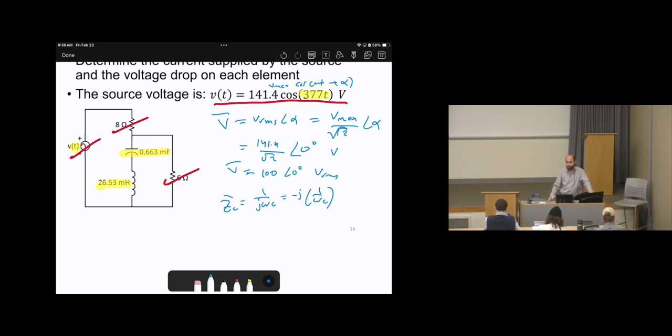It's given in an indirect way. So some of the tricks, they say, okay, there is no information about the frequency, then we will assume it is 60 Hz. No, it's given in the cosine, in the time domain expression. So this is one of the tricks that you need to figure out. So here we realize that omega equals 377 radians per second. Again, it's given in the time domain expression. So if the frequency is not given, look in the time domain expression to see whether it is given or not.